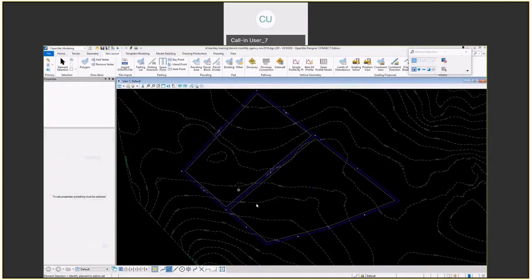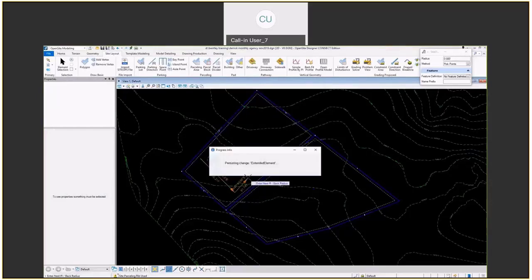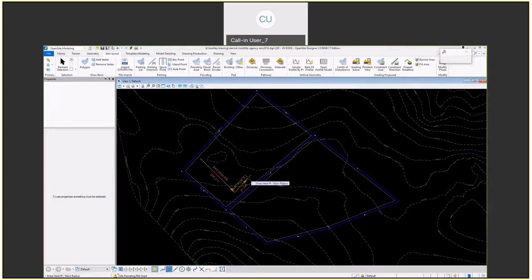So if we had a right-of-way coming through, we're doing a take. If I want to start creating these parcels into sub-parcels, multiple pieces, there's a thing in here called parcel divider. And this is nothing more than a line that I can trace across the top of a right-of-way. You want to pick the parcel you want to affect, and then you want to draw the line. You don't even have to be exact. It will extend it all the way across. So you can make any parcel.